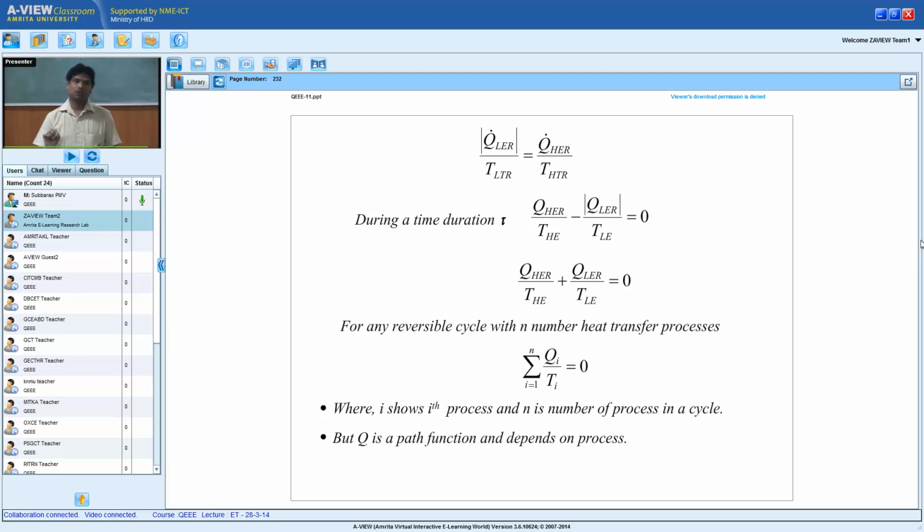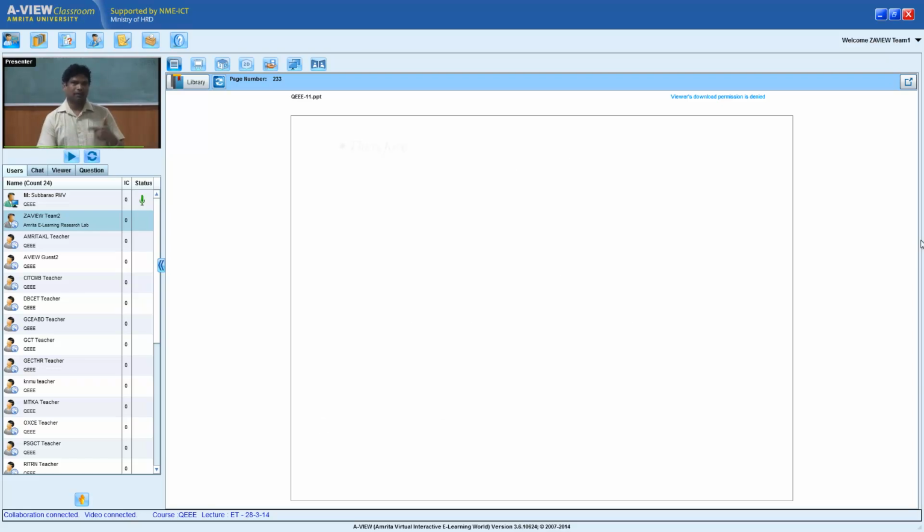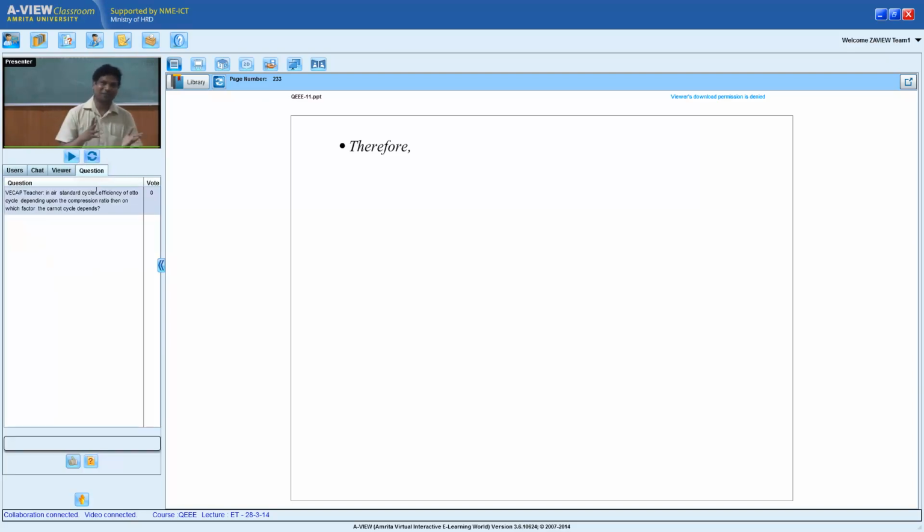But 1 to 2 have one temperature, which means there is some dividing of the heat transfer. Instead of dumping all the heat transfer at once, you try to divide the heat transfer process. That's why in a modern steam power plant there is an economizer, some heat addition, there is a boiler, some heat addition, there is a superheater. Within the superheater, they will have a low temperature superheater, intermediate temperature superheater, high temperature superheater. They redistribute. Why? If you redistribute, you can try to achieve some possibility of uniform temperature maybe.